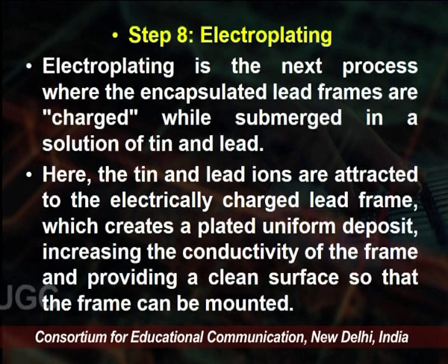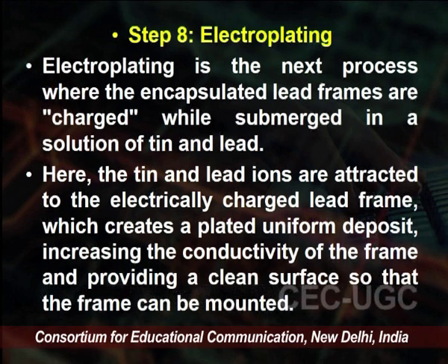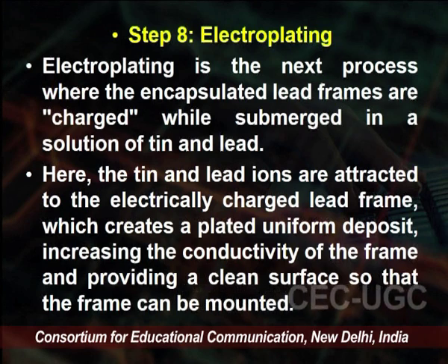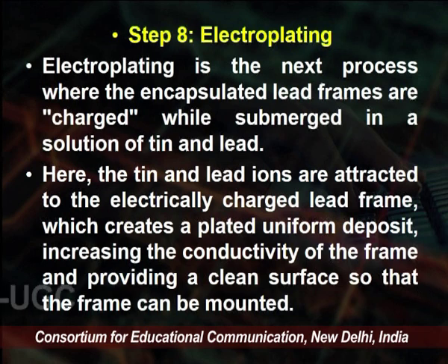Here, the tin and lead ions are attracted to the electrically charged lead frame, which creates a plated uniform deposit, increasing the conductivity of the frame and providing a clean surface so that the frame can be mounted.